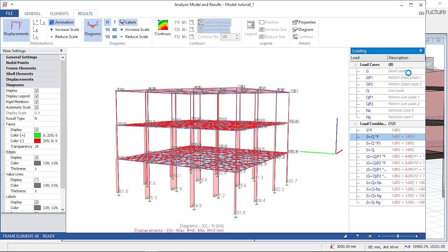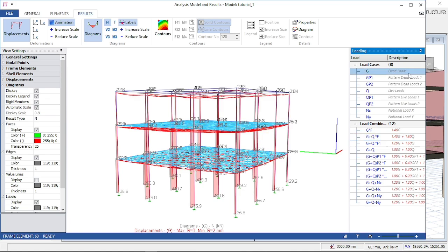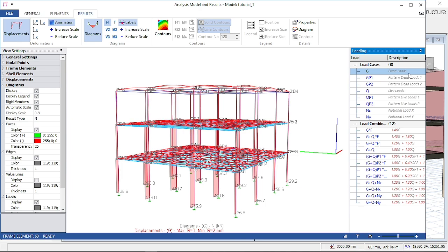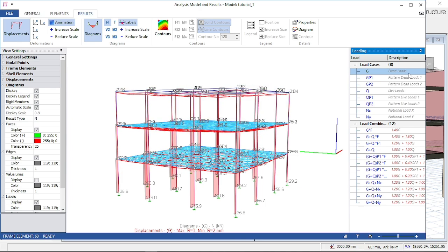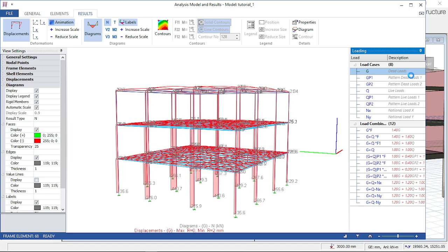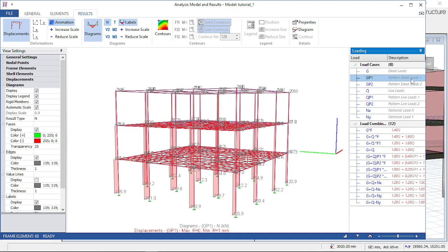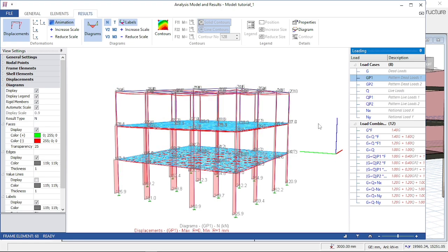So this will give you a guide after designing, in case you see any deflection in one or any part of the members more than any other member, you should mark that particular member. The design might show pass, but here will give you a guide as an engineer to know which column is not okay, which beam is deflecting more than any other beam. So that will be your guide. Then you just check.